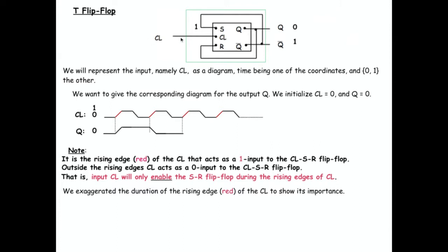It will get ANDed with the 1 in the clock, and Q will become 1. And Q prime will become 0. So Q became 1, and it's going to continue to be 1 until here, and then it will become 0 again.